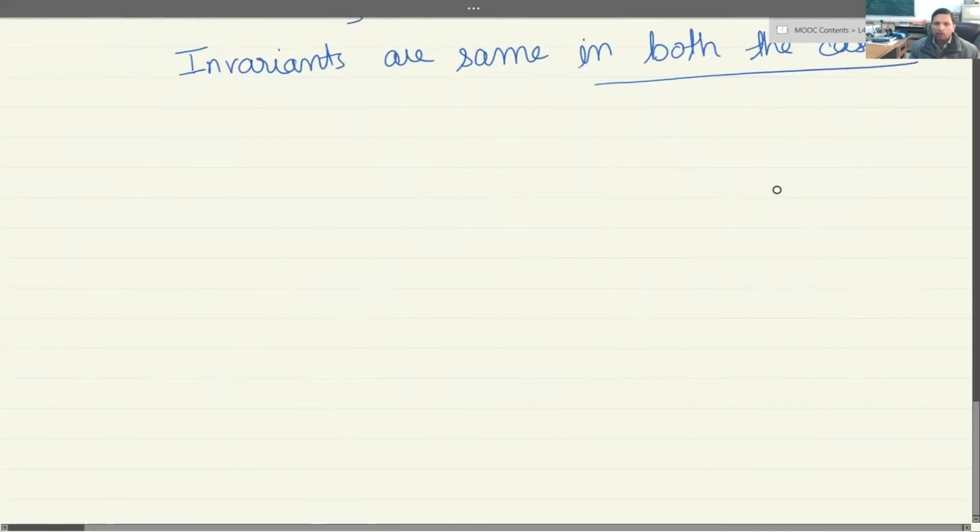Okay, so now moving on, we will look a little bit more at the principal stresses. As I mentioned earlier, when we are talking about the principal stresses, they are normal stresses when there are no shear stresses, and there will still be 3 in number for the 3 different planes.